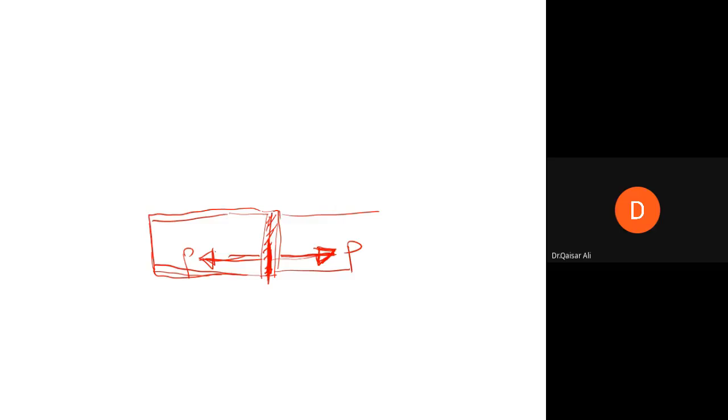As I said earlier, in the lower part of the beam there will be tensile stresses, and these tensile stresses are acting along the length of the beam because the elongation is also occurring along the length of the beam. So when the tensile stresses stretch the beam fibers in the opposing direction, a crack will appear perpendicular to the direction of tensile stresses like this. This is a beam.